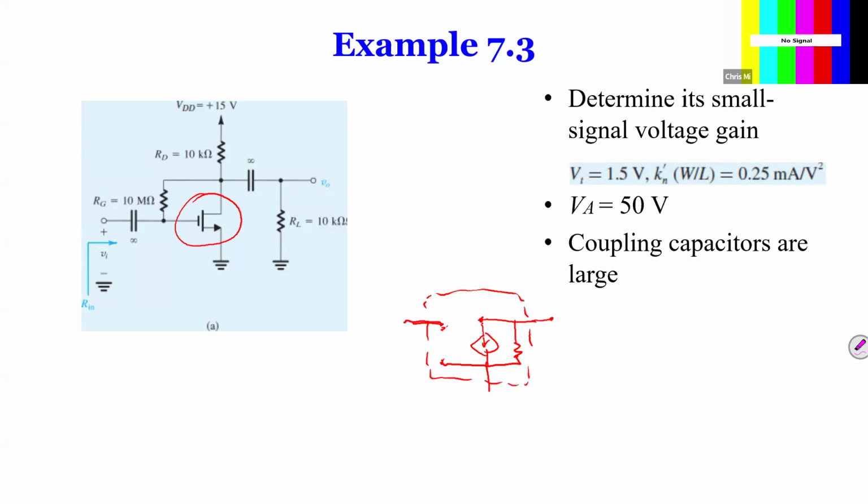Okay, we got that. So now let's look at what is connected at the gate. First of all, the gate has a cross there. Let's go beyond the cross. We have a capacitor, which is a short for AC, and then we have the voltage input. That voltage we call VI. So we have a short circuit here, and this C1 is infinity.